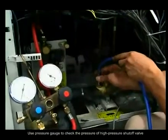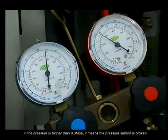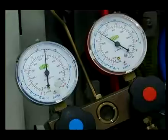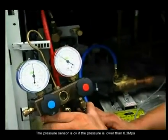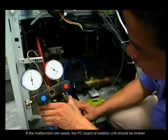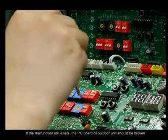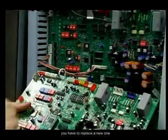If the pressure is higher than 0.3 MPa, it means the pressure sensor is broken. You have to replace it with a new one. The pressure sensor is okay if the pressure is lower than 0.3 MPa. If the malfunction still exists, the PC board of the outdoor unit should be broken. You have to replace it with a new one.